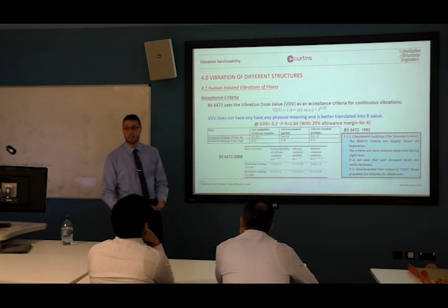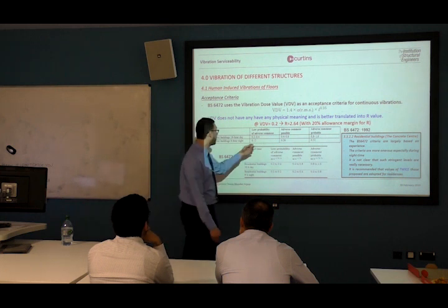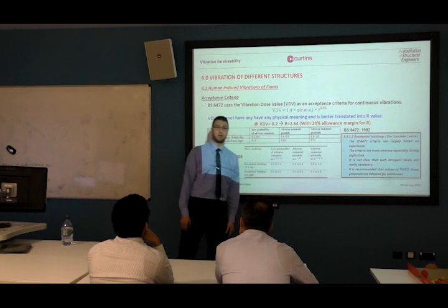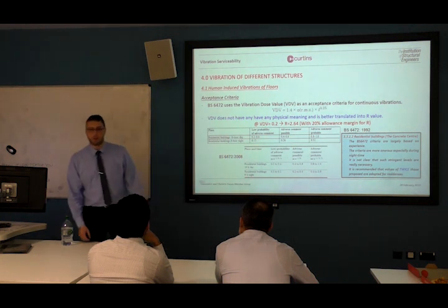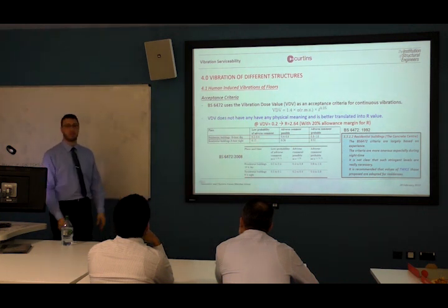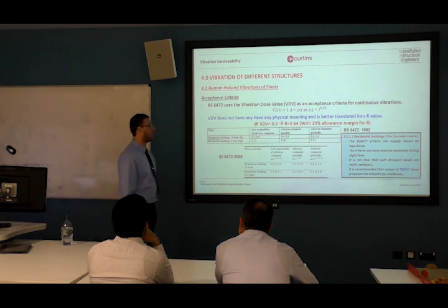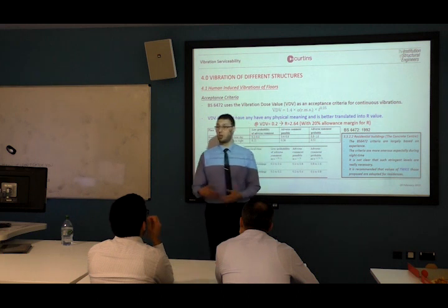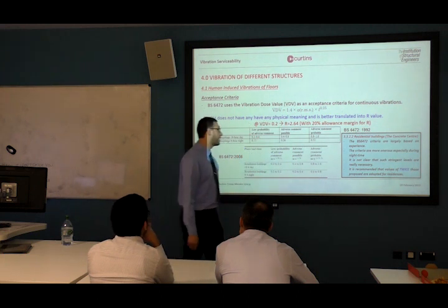It's extremely difficult to achieve. So 0.13, if you translate it into R value, is about 1.4, and it's very difficult to achieve actually. We don't need it, so let's take twice of it.